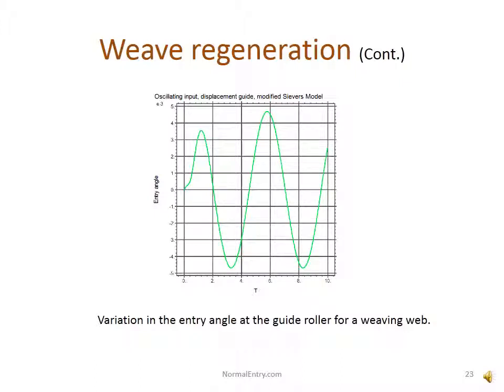This angular variation, unseen as it passes through the sensor, is passed through to the downstream end of the exit span, where it alters the entry angle there and causes tracking motion, thus regenerating the lateral error. The variation then passes in the same manner to the subsequent spans. Increasing the accuracy of the guide system won't help because it can't control the slope of the sensor. And the video in the next slide is an animation showing this behavior.